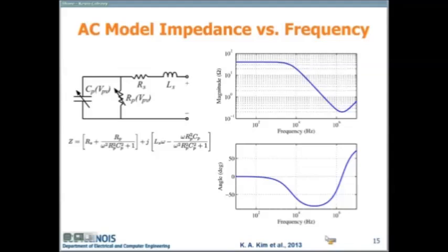The way we do it, we put a scope on the AC signal on the voltage waveform and the current waveform, and we look at the amplitude, and that's a lot easier to do signal processing on. I looked at trying to do the phase difference, but the phase doesn't go all the way to 90. This is from negative 90 to positive 90, and it's not labeled well.